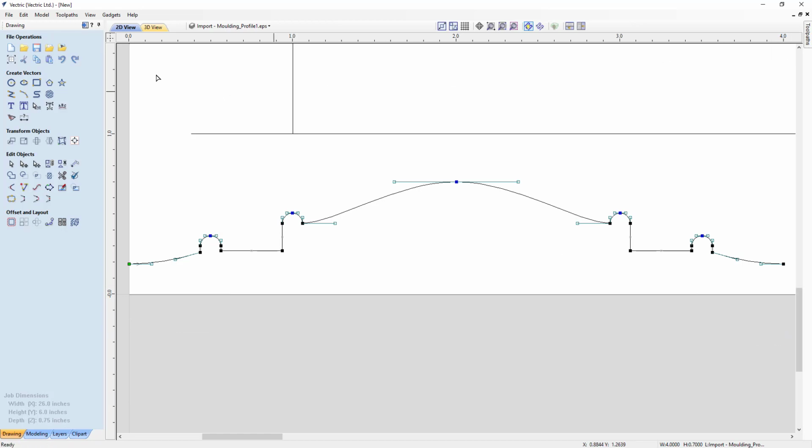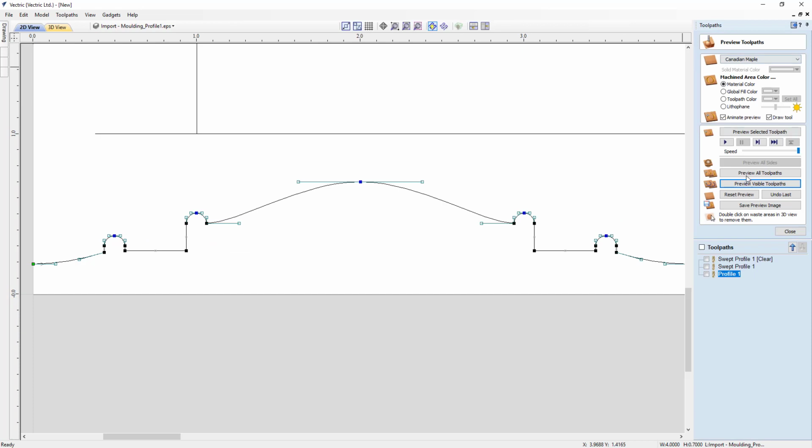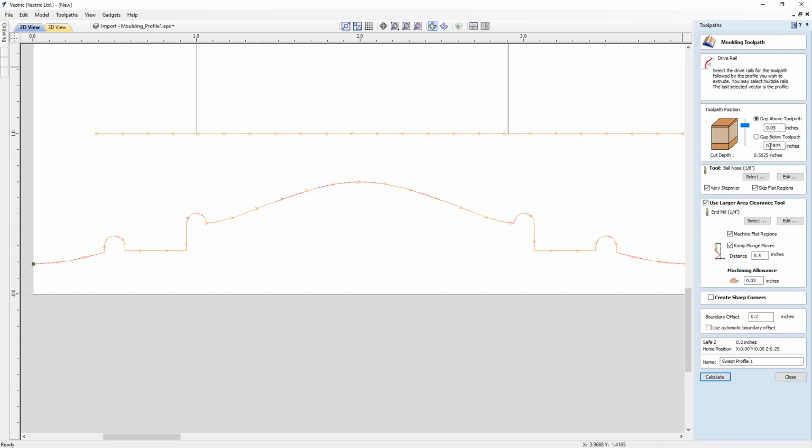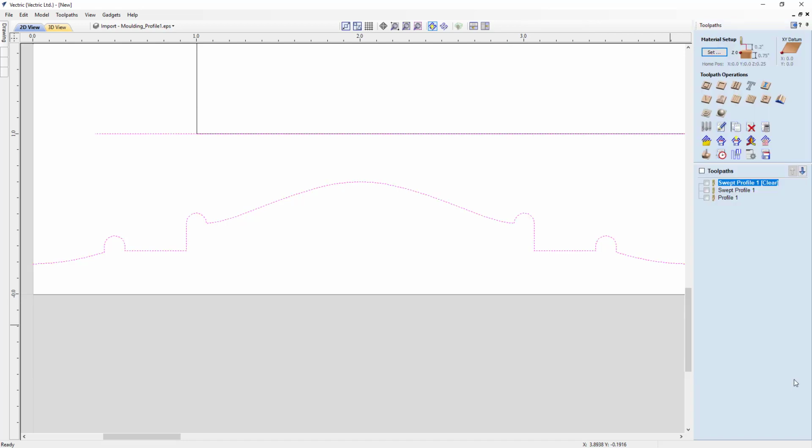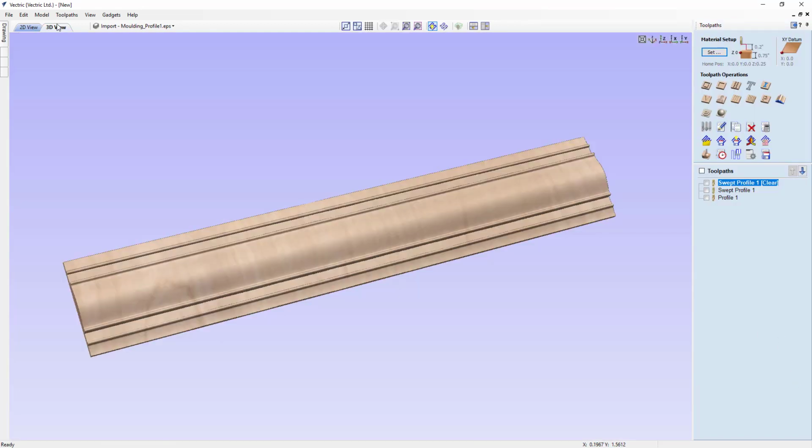And now if we go back into our toolpaths again, double click on this, you'll see that our position has now changed. So it's remembered that we want our top gap to be 0.5 and the remainder here is actually the 0.7. It's up to you how you draw this, but it is important that we point out that you don't need either one of those legs on there to use this particular option. So let's close this down. Go back to our 3D view.